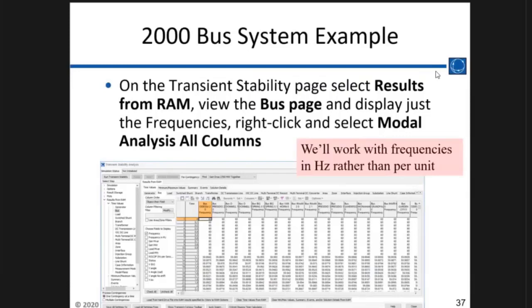So I just did a transient stability run. I don't have time to go through all this on all my runs. So can you do this for me automatically and say, hey, your worst mode, your worst damping is 4%, and that quantifies that run? Because you know, the damping's going to change as you put different events on this system. Maybe you're taking lines out or different operating points. So at least we can quantify it for you.